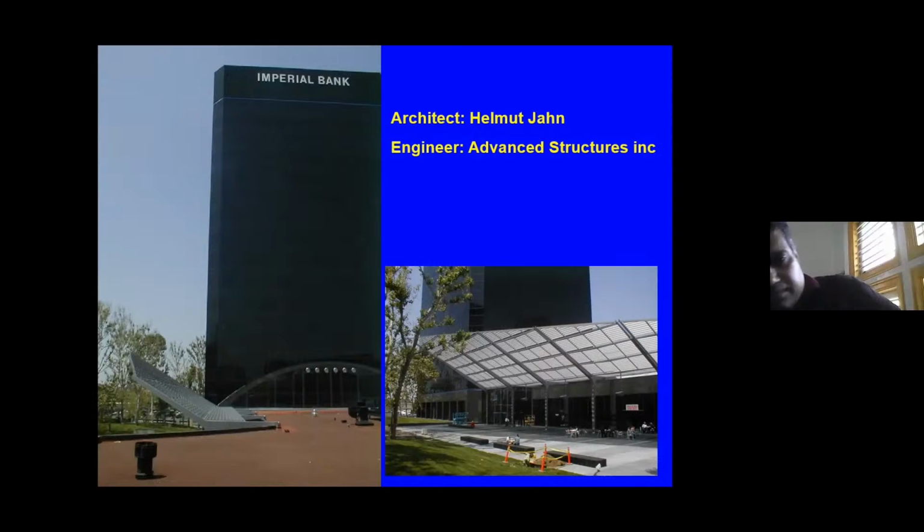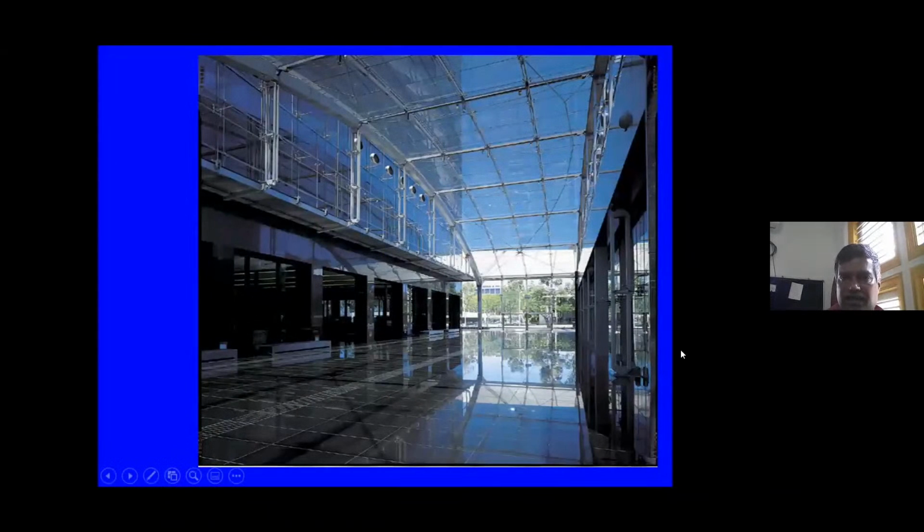It's an interesting project seismically, because what we are trying to connect is two buildings which have a different time period in an earthquake. As I told you previously, the tall building, about 20 stories, would take about 2 seconds to make a complete oscillation in and out, and the short building would take only 0.2 seconds. So how do we accommodate this kind of uneven movement in two buildings? This lobby is actually the passage that connects a 1-story building and a 20-story building. So how do we do that?